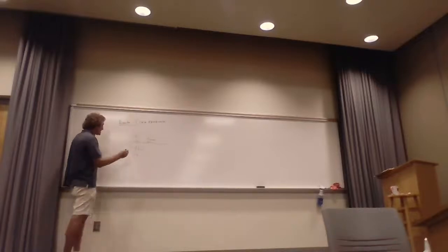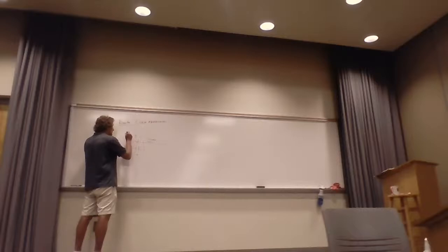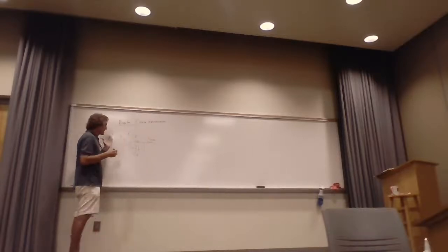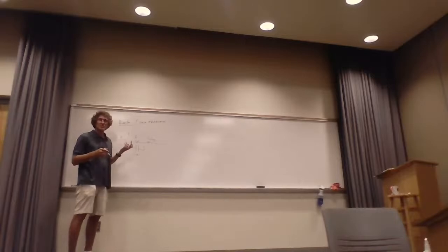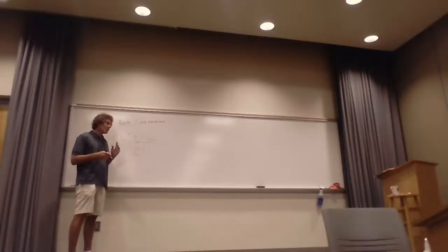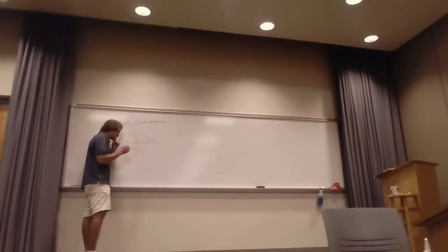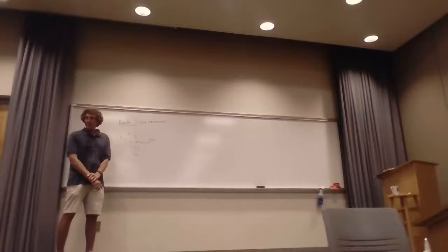Whitmore's book will have the capacitance here as some unknown capacitance. And here's why. If you think about a current I flowing here, you're going to develop a voltage across here, plus and minus. Anytime you have a difference in voltage, you have some charge separation, and we quantify that with a capacitance. If you look at his book, he has a little L sub internal there. Don't even bother with that. This is typically the way it's shown. Can you all see that in the book?